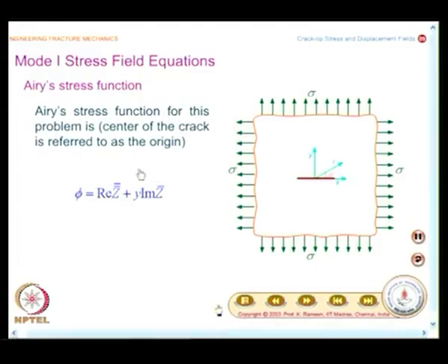See, in all our development, once the stress function is specified, everything about the problem is known. In our earlier discussion on review of theory of elasticity, I just focused on certain salient aspects. I have not gone into the details of it. Now, when we take the problem of a crack, we would investigate whether the function phi satisfies the biharmonic equation or not.